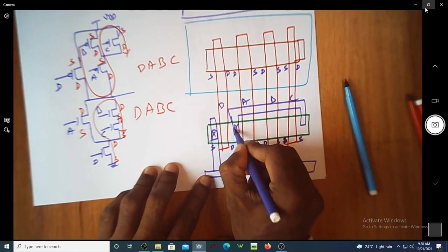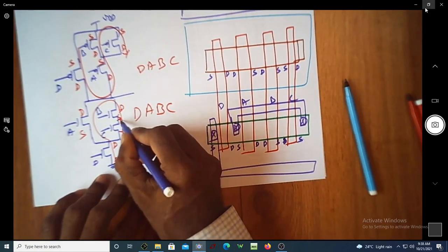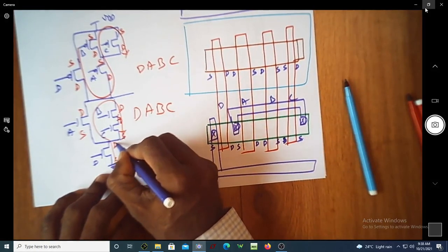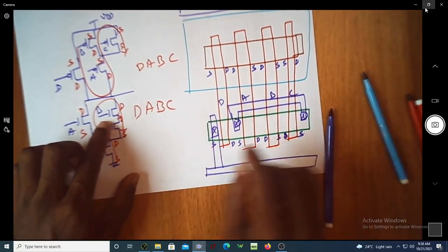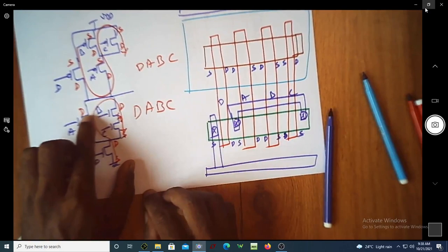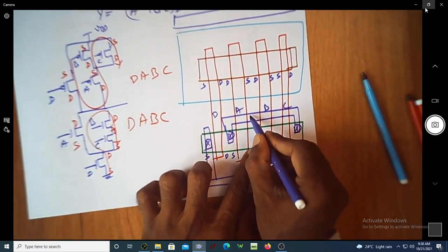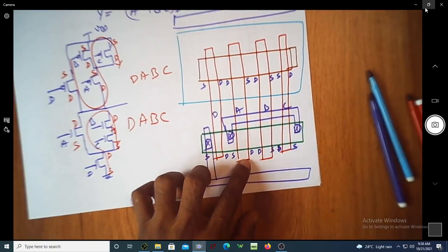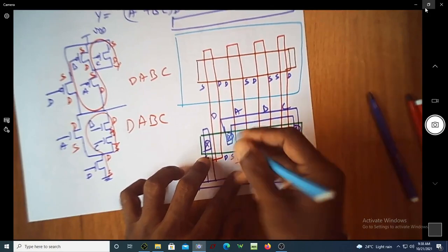This will actually establish this connection, because the path is not closed here, so this has to be done here. So this is that connection. Then the final output is there in this drain. Since this is your output point, and you already have a metal one, you may have to use other metal too. Okay, let us do that later.